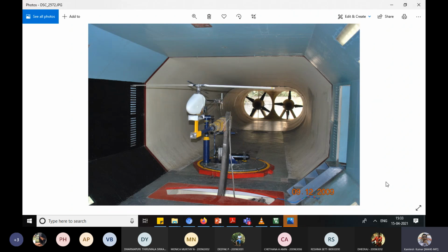So all the sensors will give you voltage data, and that voltage data will further be converted in terms of G or maybe pressure. Based on the further mathematical model, you will get CL, CD. I will show you what parameters, what type of data is generated from this. So that is one thing, and this is the static.